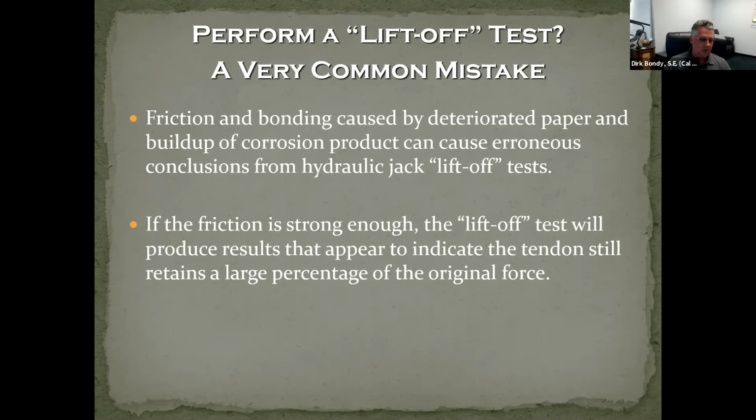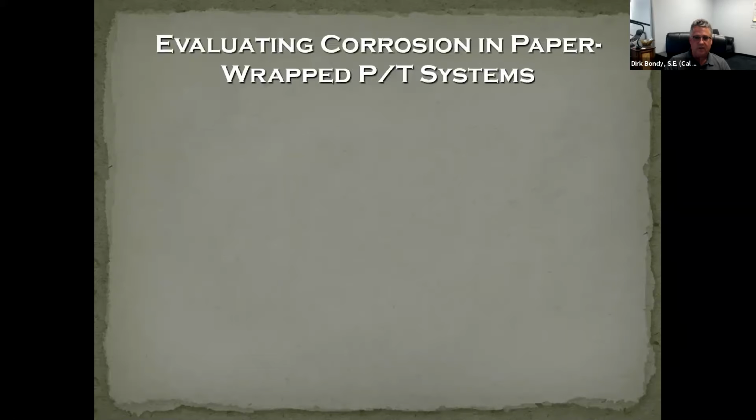The best ways are simply getting in there with a screwdriver and trying to move, or one of those car jacks, trying to just see if you can move the tendons. That to us is the best indicator of whether or not there is pre-stress in the tendons.